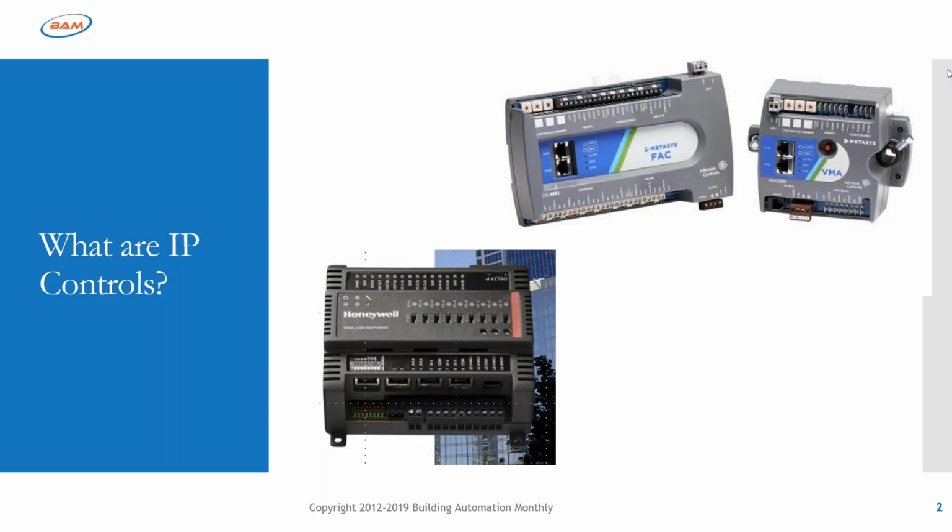What is the most common type of troubleshooting for BAS IT? Oh, my goodness, there's so many. It depends on if you're talking about compute or data or application or network. It just depends on the domain. But when I think about troubleshooting and I think about BAS, if I think where most people spend their time, it's usually on the network. It's trying to figure out routing issues, trying to figure out BBMDs and BDTs. That's where most BAS folks have trouble.